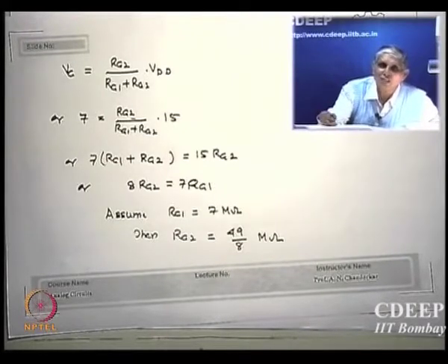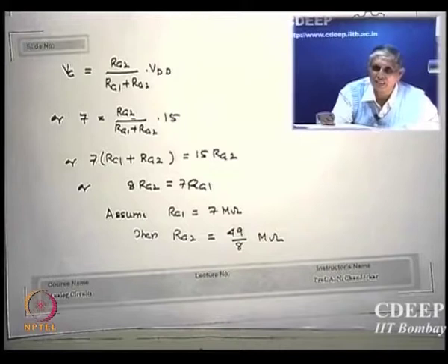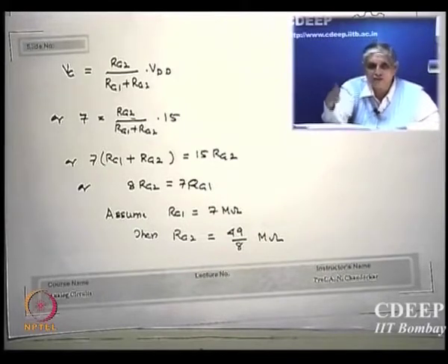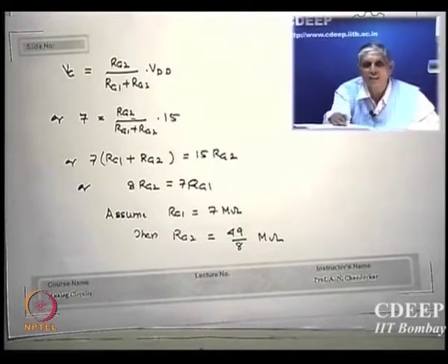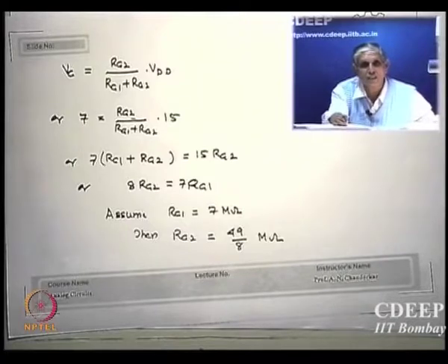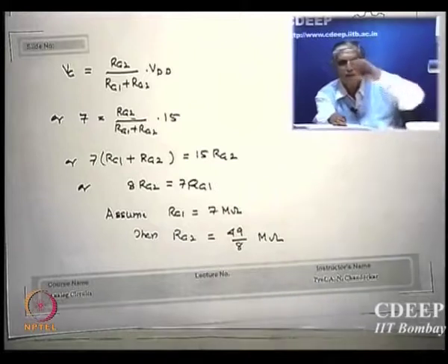gm decides what? The gain. So essentially this IDS choice is the gain requirement. Is that correct? The bias point which I fixed is essentially based on some gain which someone is asking me to design for. Is that clear? So it is an inverse problem, you got it?